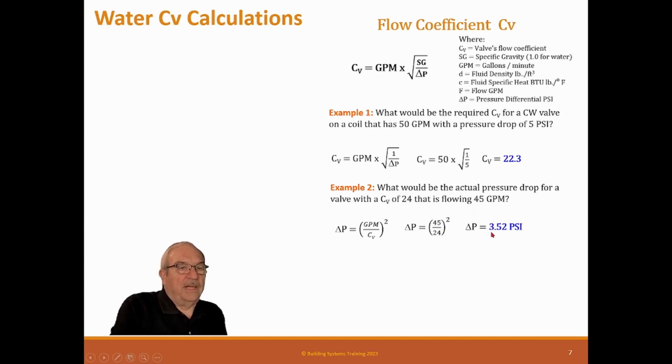So if you did that and this coil had a drop of 10 PSI, this would not be a good valve. This valve would be a big problem. So the reason this is all kind of important is the control valve is absolutely the most important part. But also when you missize a control valve, and if the designer missized it, didn't realize it, and used that pressure drop, his pressure calculation may be off.